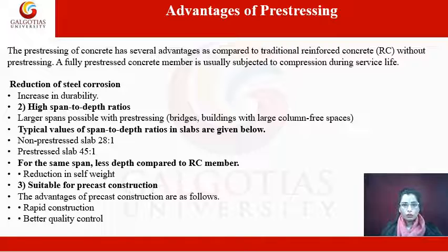So here we have the advantages of pre-stressing. The pre-stressing of concrete has several advantages as compared to traditional reinforced concrete without pre-stressing. A fully pre-stressed concrete member is usually subjected to compression during service life. The first one is the reduction of steel corrosion and increase in durability.